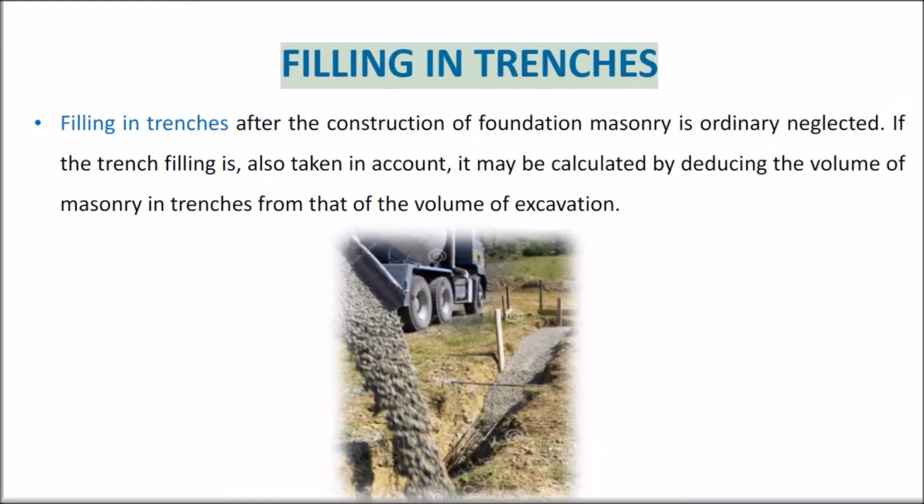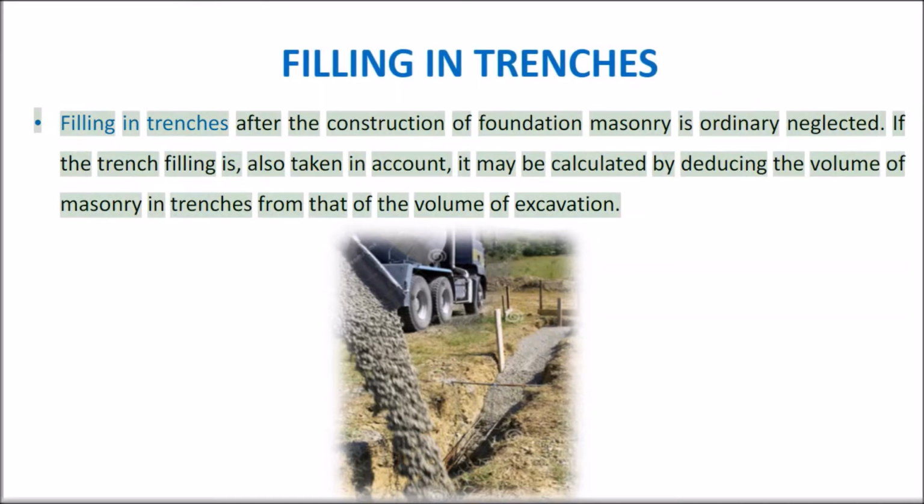Filling in trenches. Filling in trenches after the construction of foundation masonry is ordinarily neglected. If the trench filling is also taken into account, it may be calculated by deducting the volume of masonry in trenches from that of the volume of excavation.